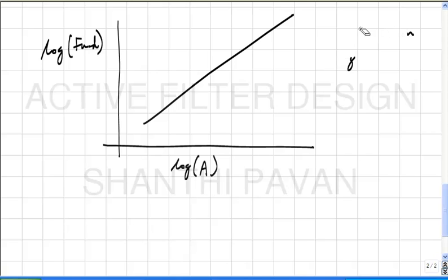Now, what do you think will happen to the intermodulation components? All the intermodulation components are happening because the signal is beating with itself, so it's proportional to A cube, correct. So what will the strength of the third harmonic amplitude be?